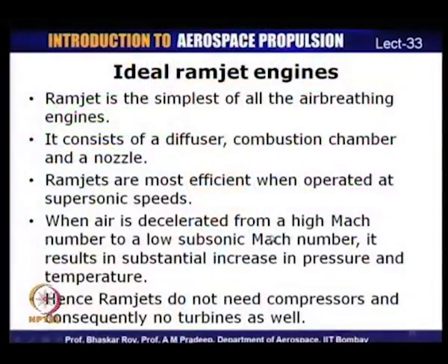A ramjet has to be taken to reasonably high Mach numbers or speeds before it can start generating thrust. Once the ramjet reaches a certain Mach number, the compression in the intake is high enough that you can have stable combustion in the combustion chamber, and so the ramjet can start operating. So, let us take a look at some of the salient features of a ramjet.